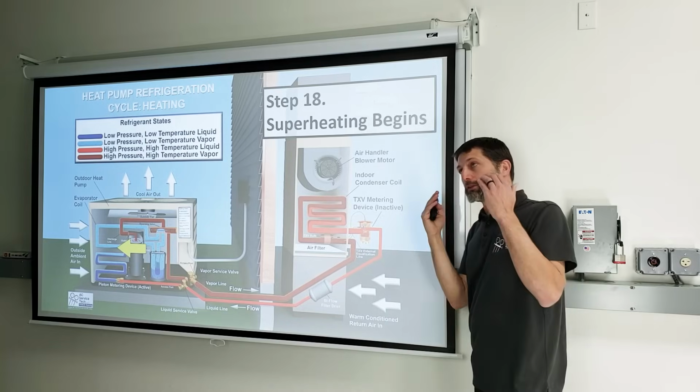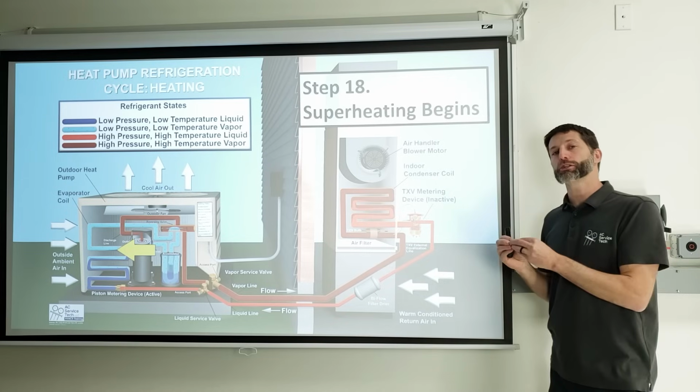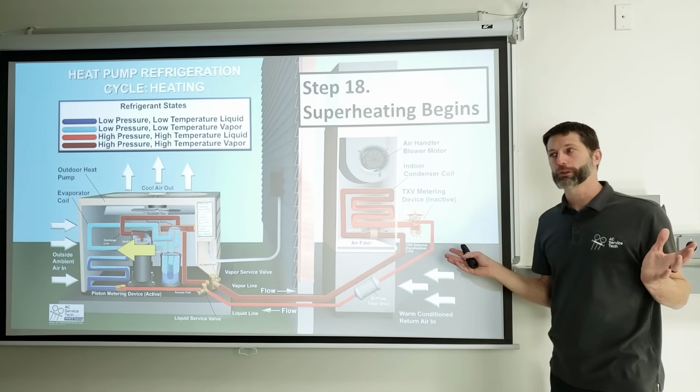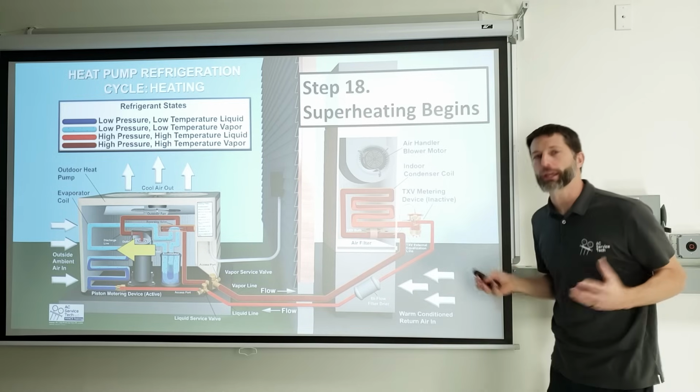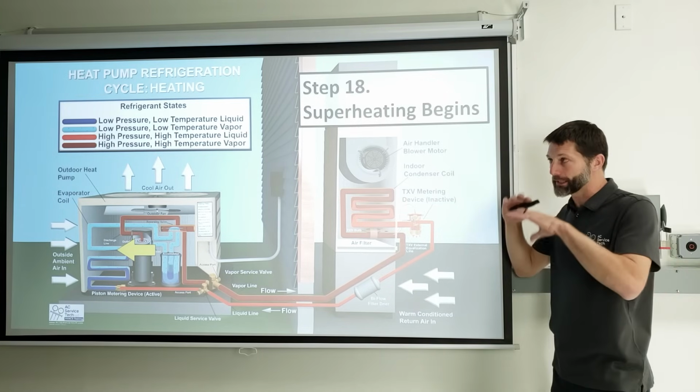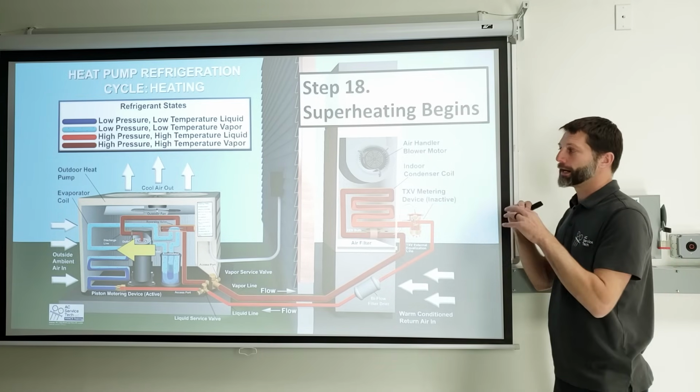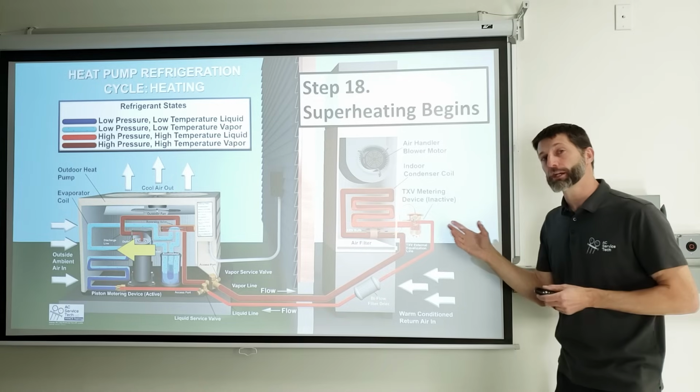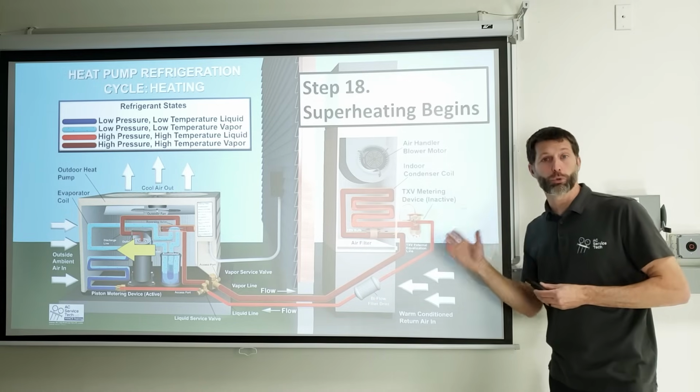You have to think about this: if the refrigerant didn't phase change and it was just vapor all the time, you'd be able to absorb almost no heat. You have to think that the saturated refrigerant and the phase change, that is the secret to this whole thing happening.